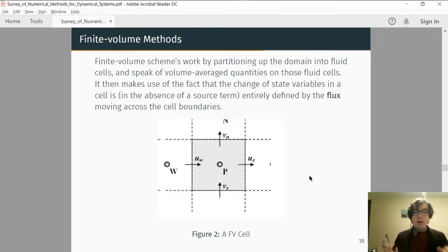And one thing, like I said, if you try to use the wrong finite difference scheme for fluid flow, it will explode and your error will be infinite, right? So something they use to fix that, another scheme they use that is stable, that will not have infinite errors, is called the finite volume scheme. And this finite volume scheme is my bread and butter. This is what I solved most of those equations with that we looked at at the beginning of the slides, right?